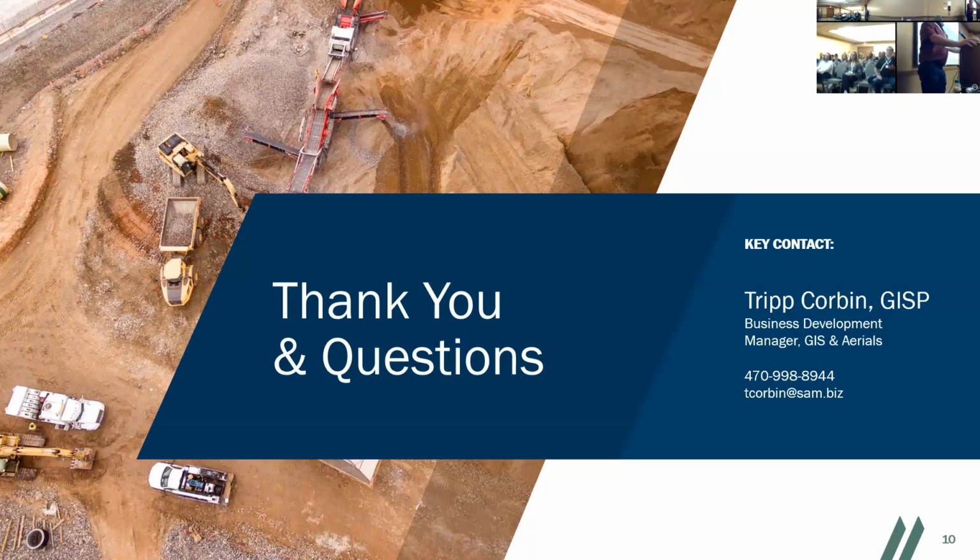That's the point. Yeah, I get what you're saying. If you're going to attribute those, then you're going to have to convert it to GIS, and the new GIS data is going to be based on that georeferencing location. So the rotation and the scale will have been adjusted, so it will not necessarily match what was in the original CAD file. So from that perspective, if you're directly attributing it from the drawing itself, then they can be different, right?